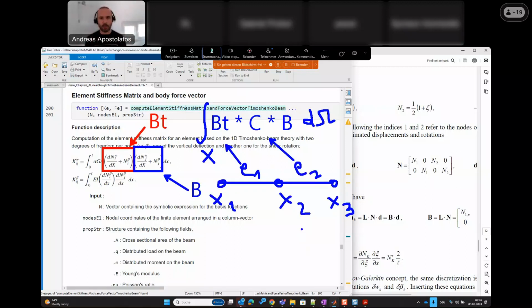This is quite important. I would really like you to understand this, because I think this is a question that may easily arise when you're studying finite element analysis: why are we evaluating the integrals per element and not at once for all the elements? And I hope the answer here is clear enough, because our basis functions, and in turn the derivatives of the basis functions, and in turn the B operator matrices, are not fully continuous throughout the whole space.